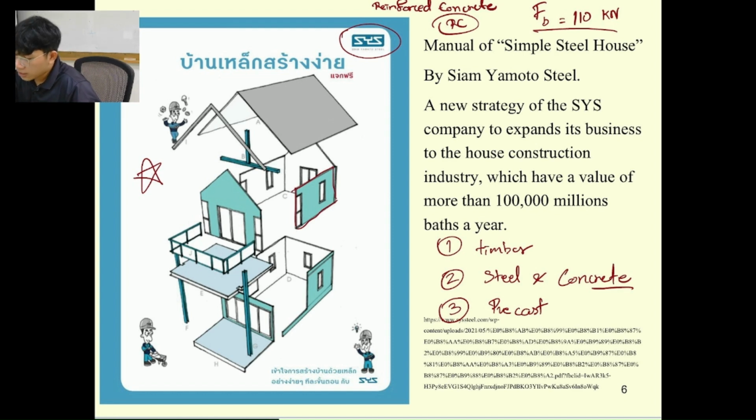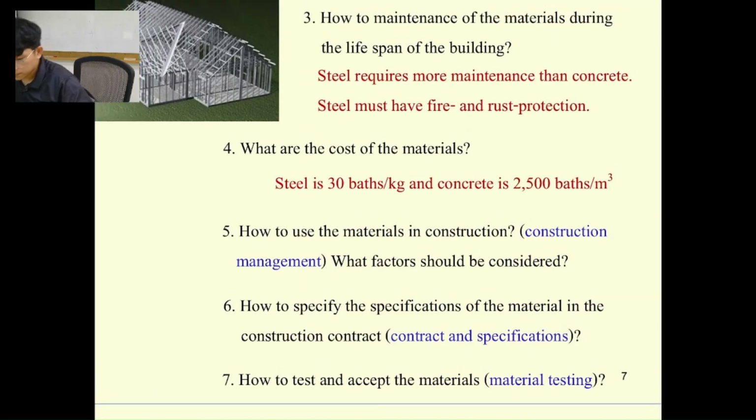So right now we are switching to precast, which is the phase 3 of construction. Even for high-rise buildings, with precast they are not going to put brick and mortar, because that is really hard to plaster. They just order it from the factory, and when it reaches the site you tell the tower crane to lift it, put it in location, and weld it. It is a lot easier and saves a lot of time compared to the manual way.